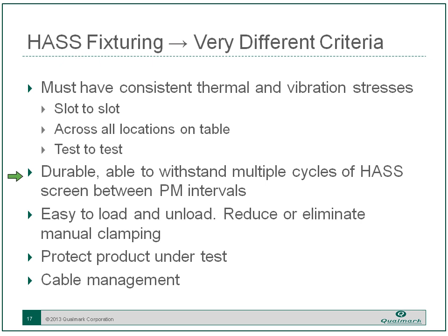They need to be able to withstand multiple cycles of a HASS screen between PM intervals. When you consider the abuse the product takes, the fixture gets beat up pretty bad. It needs to be easy to load and unload. The human factors become a significant consideration. Throughput time gets cramped if it's difficult to get stuff in and out, and also, of course, the issues of heavy lifting and the rest become a problem.